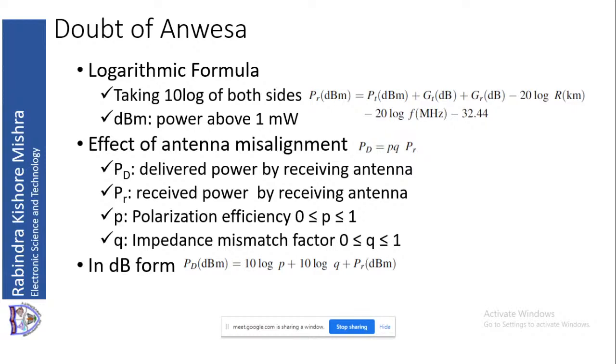In this distance there will be scattering, because fine particles will be there in the atmosphere, so there will be some loss. And there will be gases which will absorb some amount of energy. So in the path there are different mechanisms because of which there will be some attenuation. That attenuation is called path loss.